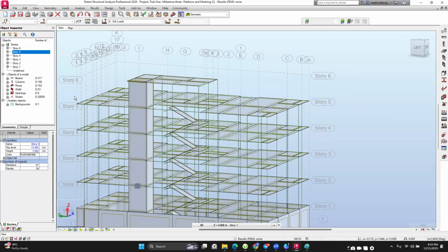It's usually just a small parapet wall that you may want to consider at this particular point. So there's no need of designing the structure with a wall at this point going up to story 6, because it's just going to be an over design. There's no harm in doing that. It's going to be uneconomical, but it will not affect your structural integrity. But if you are keen on being a bit economical, you can use a lesser load for this one.